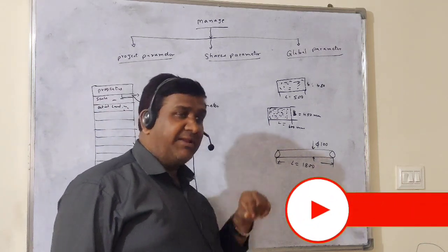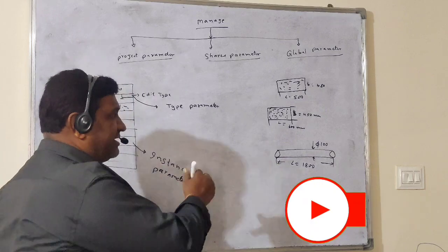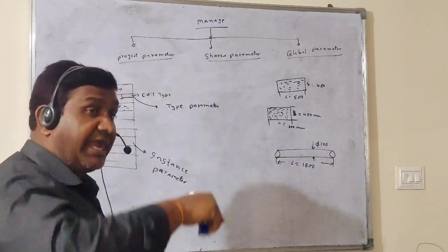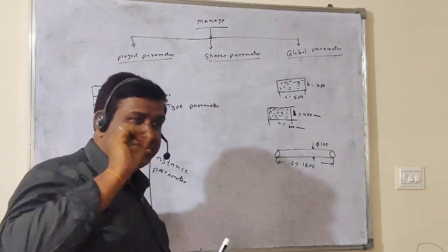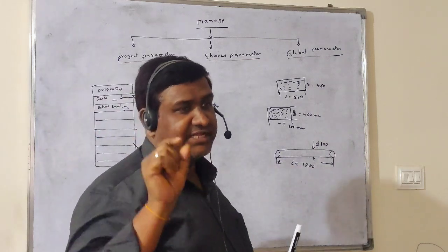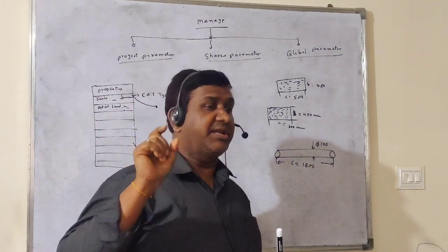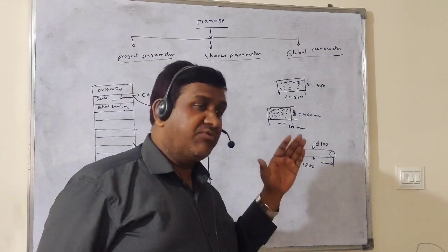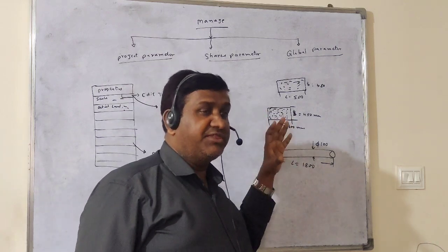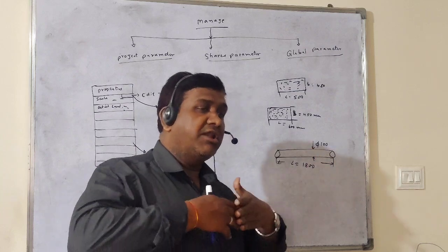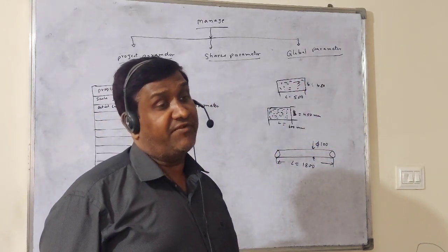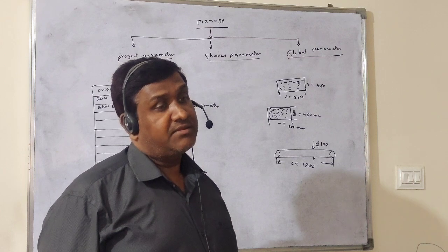But in edit type, if your parameters, the length, width, height, are in the edit type menu, and you change any value in edit type, say the length is changed from 600 to 500, then wherever you have placed the column with the same size, all areas are going to be affected.